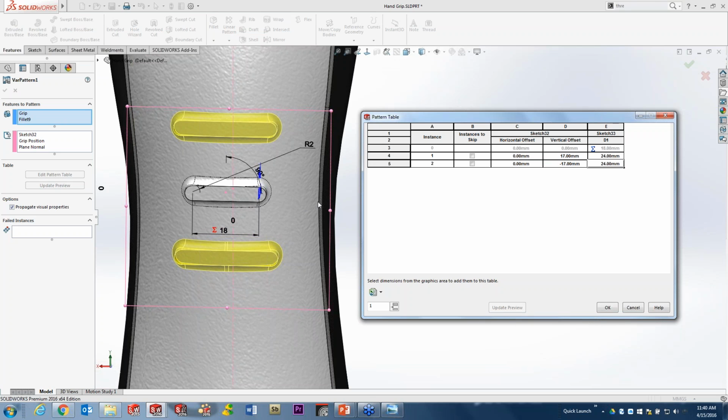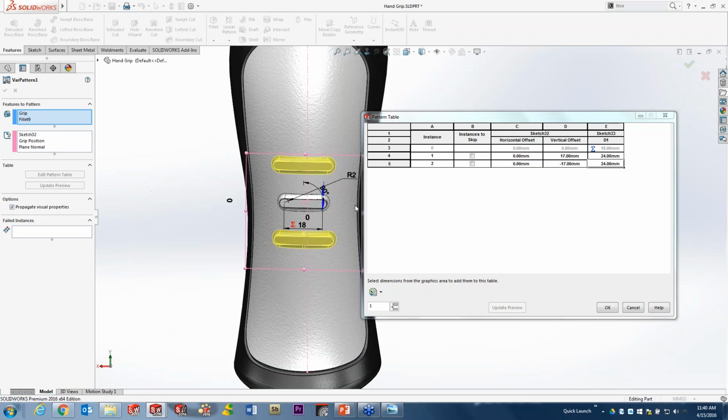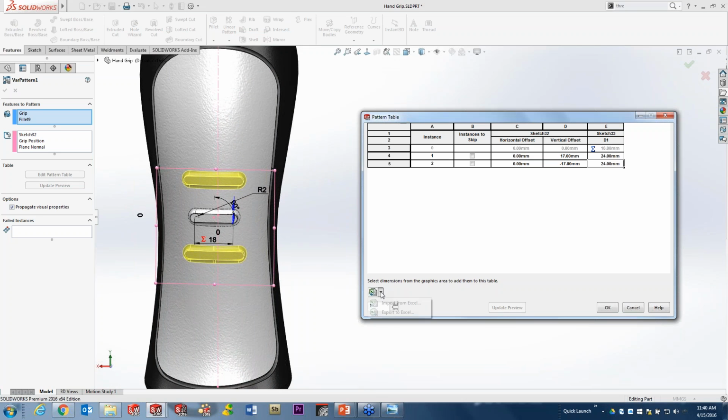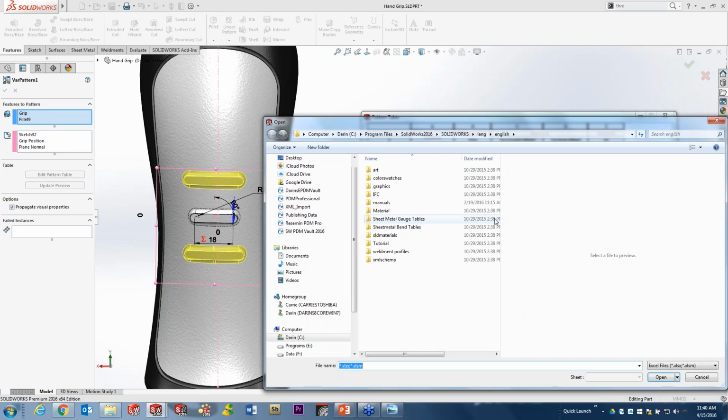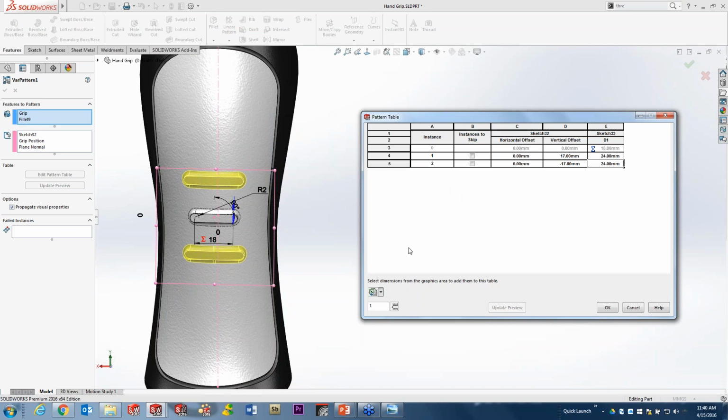Well, these patterns can get pretty heavy. You might have a lot more input than you'd like to do manually here, and that's where we now have the ability to import this directly from Microsoft Excel. When we grab this, it's actually more convenient, and I'll go back on this, to simply take what you've got here and export it to Excel first. If you export this value to Excel, then it's going to give you the formatted table that you can then modify using more formulas and other values there, and then import that table back in.